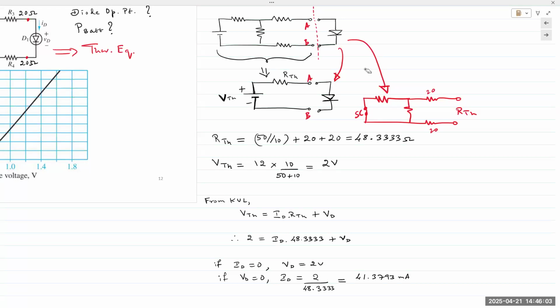All right, so that was Thevenin resistance. Now Thevenin voltage. What happens to the voltage source in the Thevenin voltage? Anyone? Now you can laugh. Nothing happens to it. We need the voltage source. If there is no source, we don't have any output. So the circuit stays as it is. If there was a current source there, we'd leave it as it is. If there's a voltage source there, we leave it as it is. Without a source, we don't have any output.